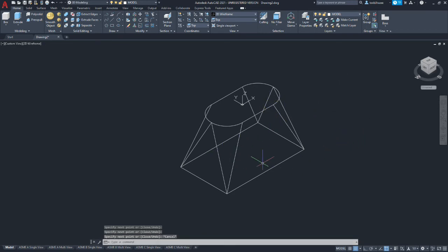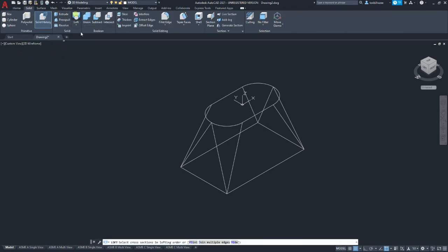Okay, so you should have triangles on the end and I guess a trapezoid on the other sides, blunt cone, whatever you want to call it. Okay. Now we're ready to loft. So we're going to go to Solid, Loft. We're going to select our rectangle, and we're going to select. Oh. Now, this is a composite section, so we need to join it before we can do our loft. So let's do a join.